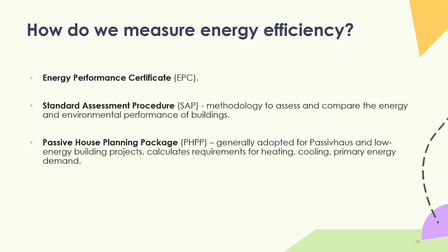When we're working in retrofit, what we tend to find is we're using RDSAP, reduced data SAP, to generate those EPCs. So they're based on a lot more assumptions about how efficient a wall is at stopping heat escaping, for example. Because, I mean, what are you going to do? Get the builder from the 1930s to come along and tell you the U value for the exact cavity wall that they built? I think not.